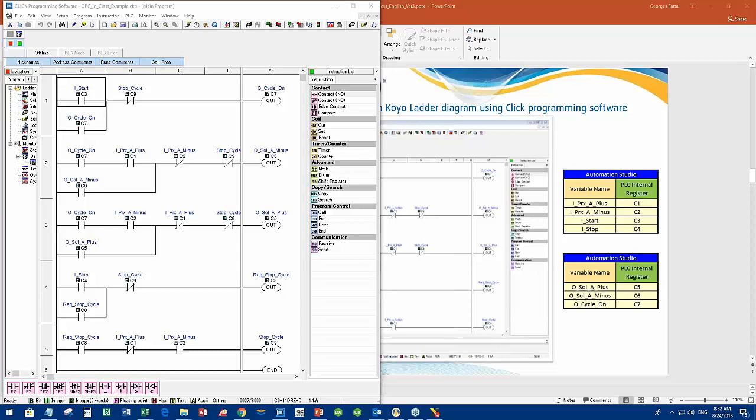Once you're going to be writing, for example, an SFC graph, instead of using these internal variables, which sometimes you may forget which device in the system they belong to, by tying it in at the beginning with this intermediate variable which carries a name that makes sense, you'll find your SFC self-documentable later on once you read it, and you'll understand exactly what's going on in the system.